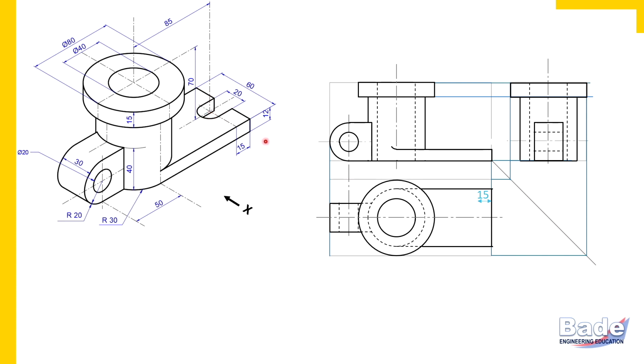Check where is its center. So extreme right 15 millimeter on the axis of symmetry. So I measured 15 millimeters, and on the axis of symmetry, this is the center line, and I have located the center. So here the diameter of that semicircle is 20 millimeters. So use radius 10 millimeters. Watch here, and complete that semicircle. Now to complete the U shape, from the ends of this semicircle, draw edges parallel to the length. Watch here. And this is how the U shape opening is complete.